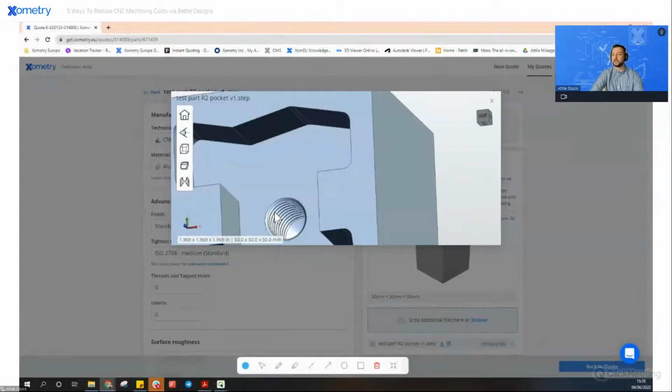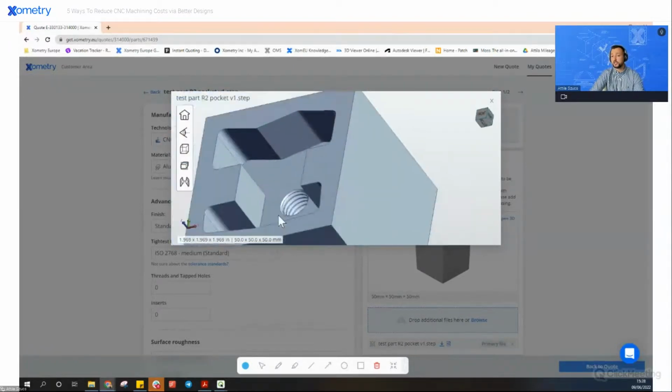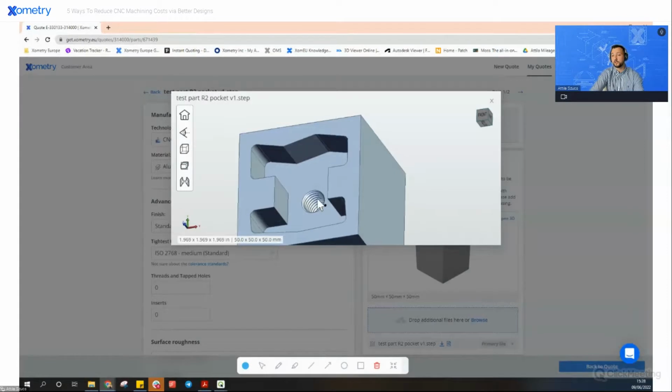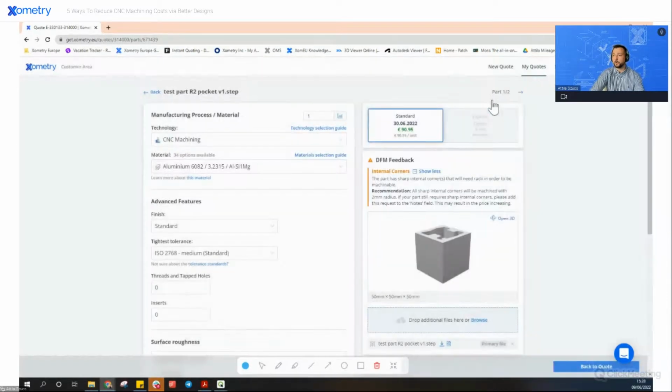Thinking of it as an undercut, the CAD/CAM software does not really like to read it. I'd suggest you put it as the core diameter of the thread and present it as a 2D drawing, stating what kind of thread it is, because the pitch is not going to be readable from the model.